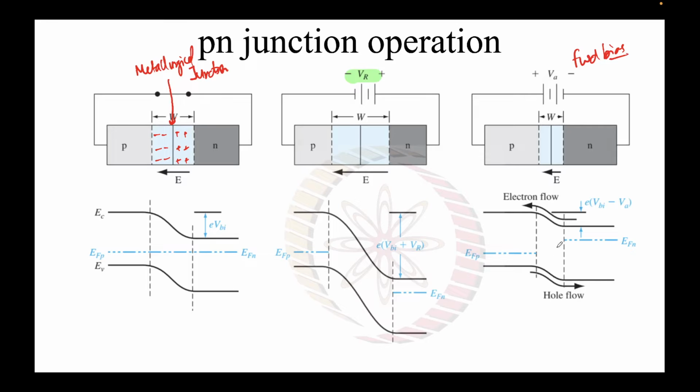And you can see the Fermi levels have now split. There is no one Fermi level, which makes sense because this system is no more at equilibrium. So we denote them as something called the quasi-Fermi levels, EFN and EFP.